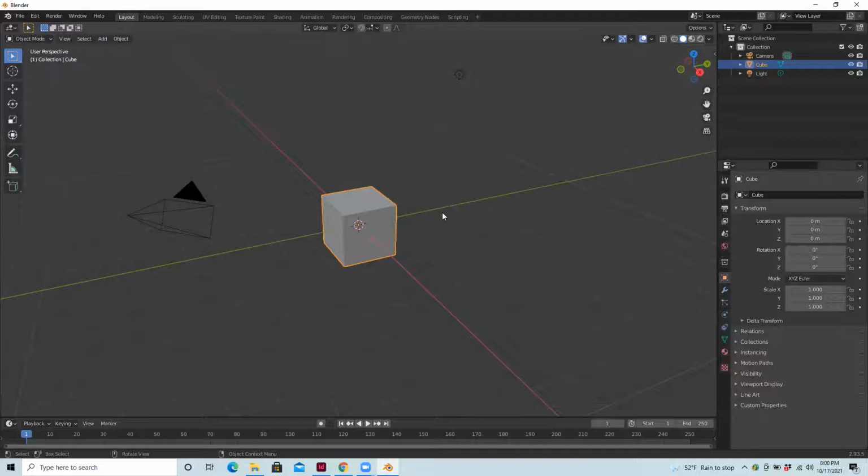But what if you want to create a new object that might involve stretching or distorting, kind of altering individual points or lines or faces on your object? And that's what edit mode is going to be all about. So I'm going to actually just try it for a second to give you the idea on this cube. Let me switch to edit mode. And you'll notice that the toolbar is impacted when you're in edit mode. We basically have additional editing tools that you'll be learning about.